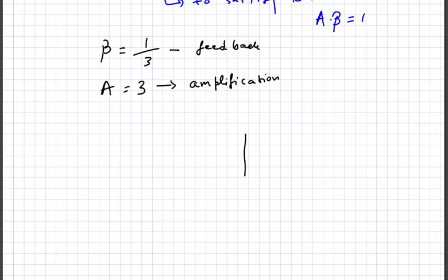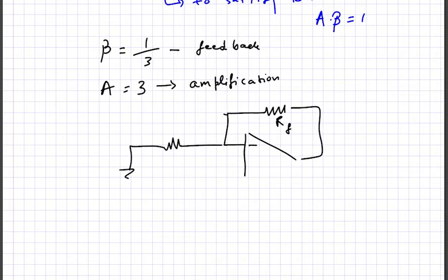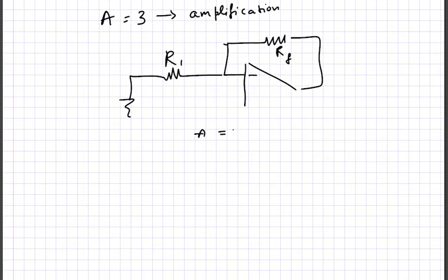You might see there the minus side of the op amp is connected through a feedback resistor and another resistor R1, and therefore the amplification is actually given by 1 plus RF by R1. So this top part tells you the amplification factor of the op amp.